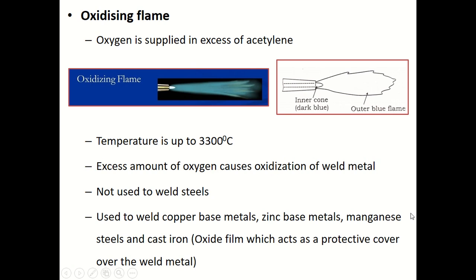Let's look into another interesting flame, the oxidizing flame. What would the oxidizing flame be? If the neutral flame uses an equal ratio of oxygen and acetylene, then what would it be? Of course, as you might think, the oxygen is supplied in excess of acetylene. When oxygen is supplied in excess of acetylene, the flame is called an oxidizing flame.